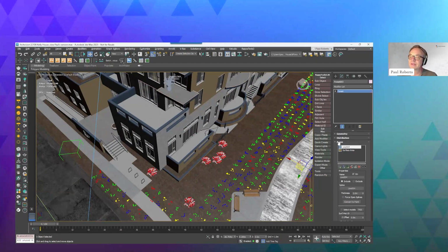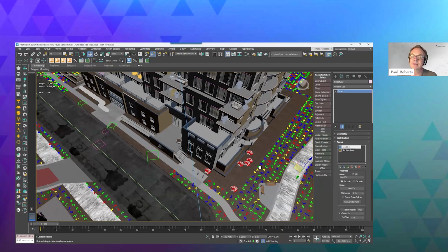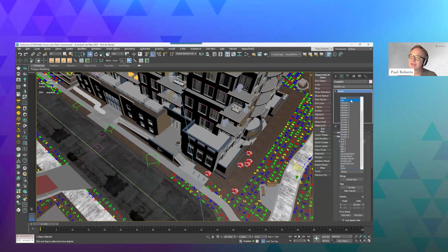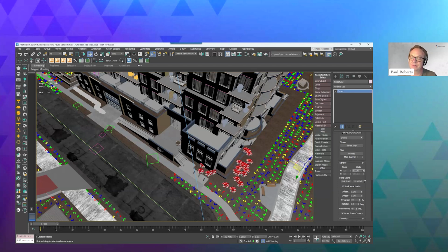And that's working, as you can see, but not a lot of shrubs. And that is because my distribution is very low. So when you get into placing plants that aren't presets, you need to set these things yourself. And so you can see the areas is where you scatter, but the distribution is the pattern that you scatter within that area. And it uses different types of maps, which we'll get into later. And then it uses a density setting. And just by dialing that down, you can see I change the density of those objects, right?